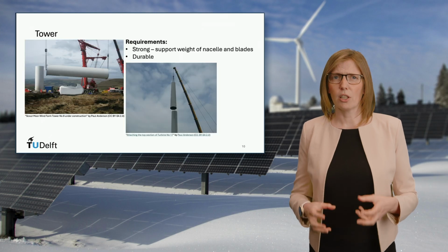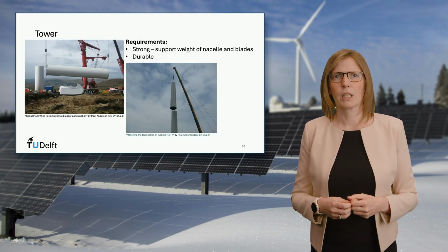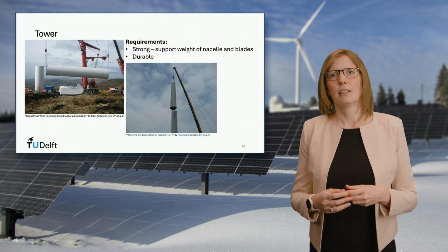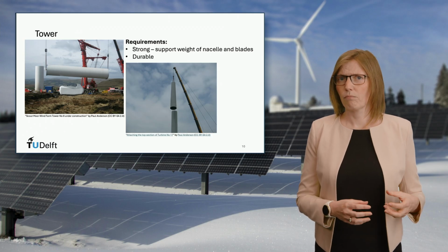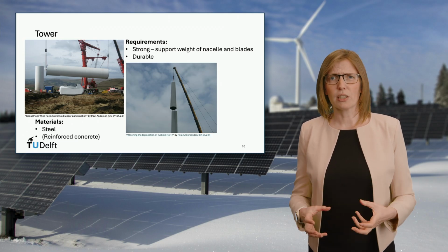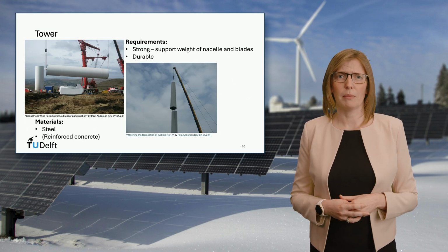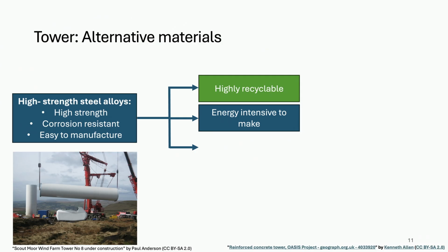The tower is another crucial element of the wind turbine that must be strong and durable. Since it supports the weight of the nacelle and the rotor blades, it is built to withstand significant mechanical forces. Towers are generally constructed from steel or reinforced concrete, with steel being the most common material. Steel is chosen for its high strength, ability to resist corrosion, and ease of fabrication.